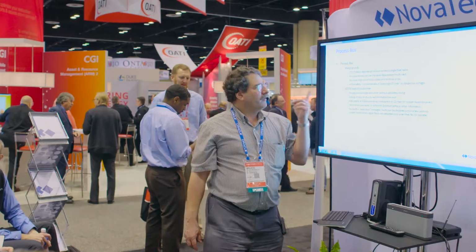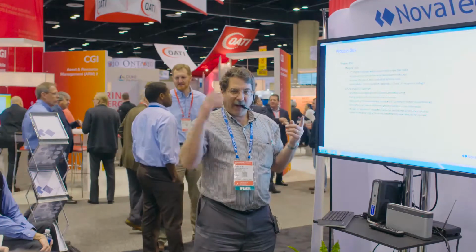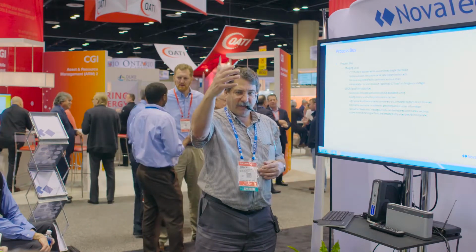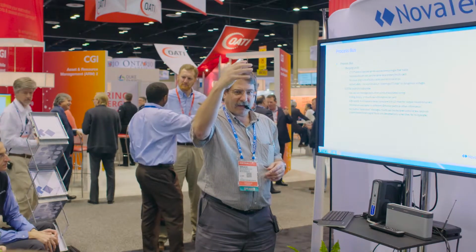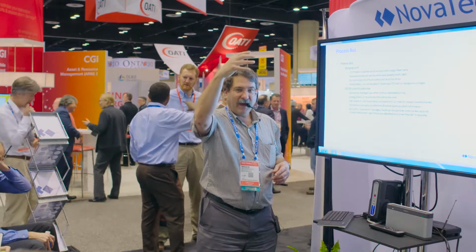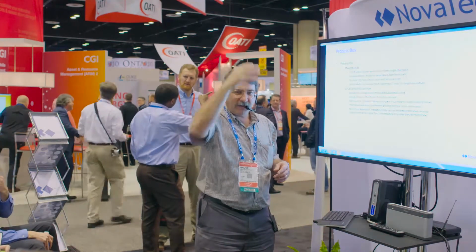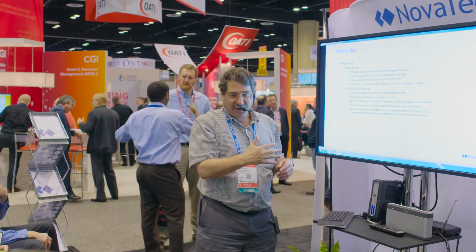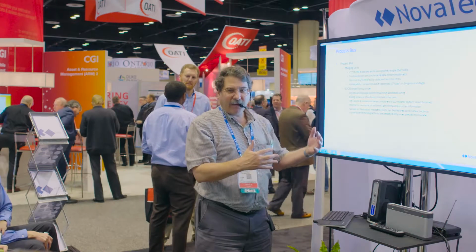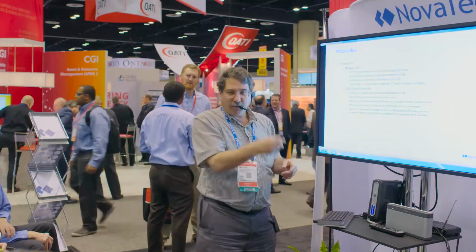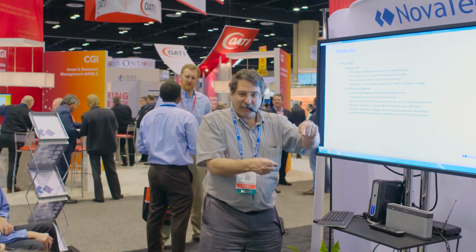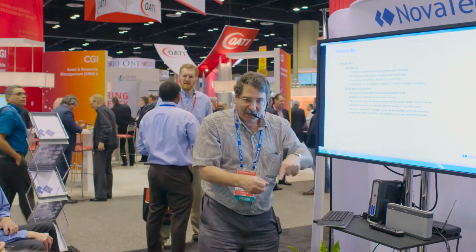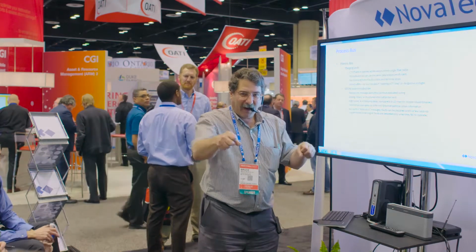Process bus, the merging units. As I said before, the idea is to digitize the data at the source. So out in your station yard, you've got your CTs and VTs that are hooked onto the primary equipment. The typical way to do it is to take all those CTs and VTs, run all parallel copper wires, some of them very thick, 10 gauge, 8 gauge wires, run them all back to the control house, put them into multiple barrier strips, and run them to all the devices on the CTs. You've got to make sure all the devices are in series, and these lengths can get quite long.